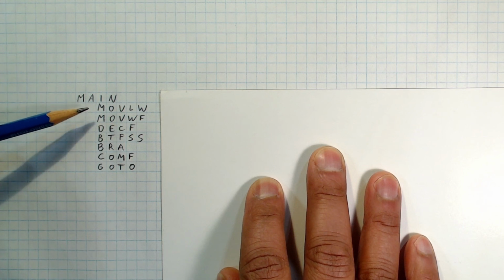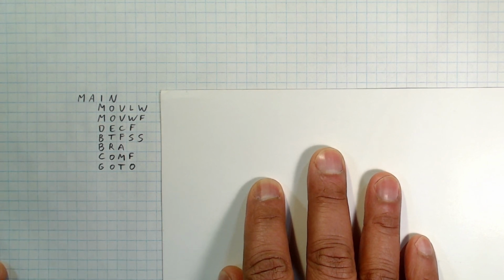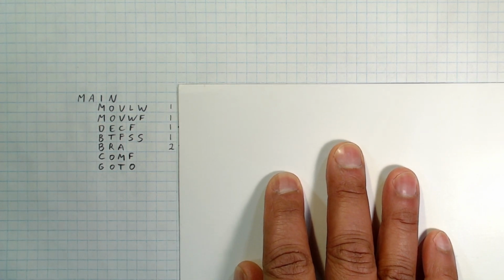So we actually need to calculate how long this entire loop takes and then figure out what value to insert in there to know how long to count that loop. This is a little bit of a messy calculation, but let's get into it. I've written out our instructions on this sheet of paper. Beside each instruction, I've written how many cycles each instruction takes.